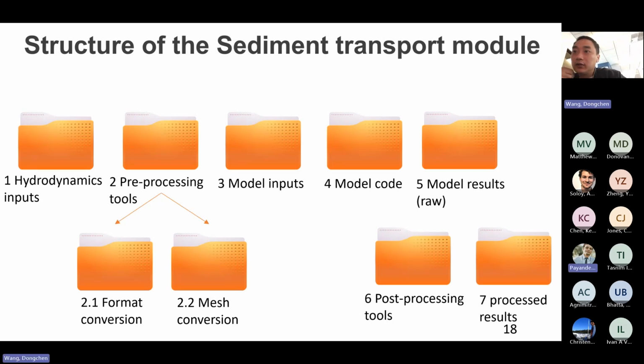The first one is maybe a question for you, Juan and Ariel: what is the main difference between the MATLAB sediment transport model and Dorado? Okay. The MATLAB transport model solves the Exner equation, and also the advection diffusion equation. Dorado is a particle tracking solver, so it's a different solver first.